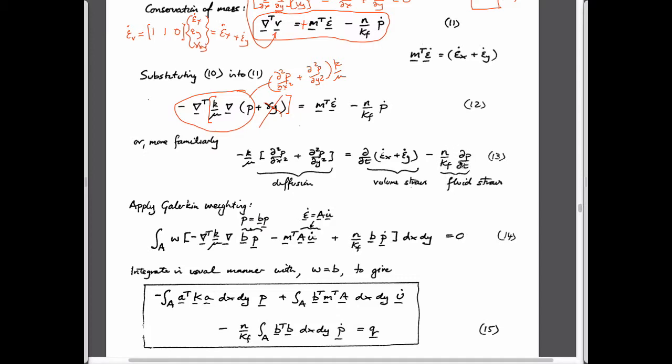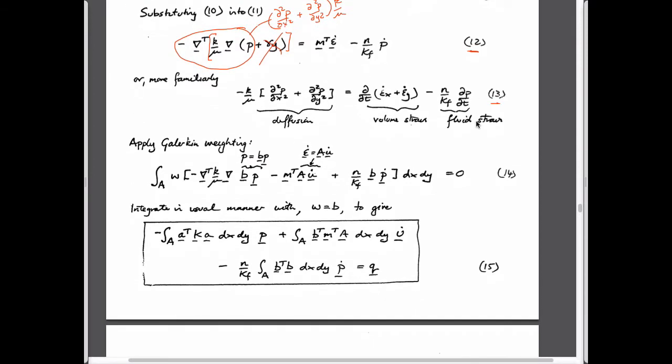So these are just the uniform fluid pressure within the system. Of course, it will be mapped by the shape functions, but if we're taking just a control volume for now, we don't have to worry about this. And these would be the strains in the x and y direction system. So this is just, I guess, equation 12, just written out in longhand. And so now we can do this heuristics that we've done before to figure out exactly what the finite element equations would be. So this is our pressure diffusion equation, second order in space, 0th order in time.